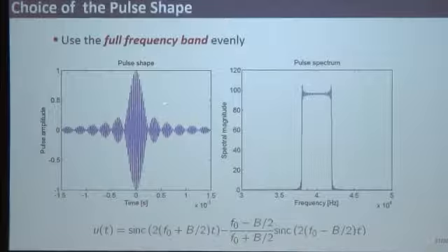Okay, so before moving on, I'll just briefly go over the choice of the pulse that we have. This is a topic in its own. Bats use chirps. We don't use chirps. Bats are much smarter, so they use chirps. We use something that's quite peaky, and it's like a filtered Dirac pulse, okay? So it's just a complete passband pulse between 38 kilohertz and 42 kilohertz that we use. I could have plotted the autocorrelation of this thing, but the autocorrelation of this thing is actually this thing.